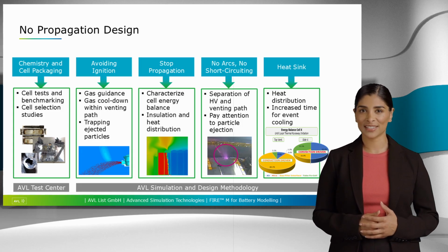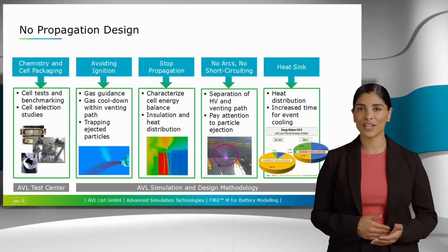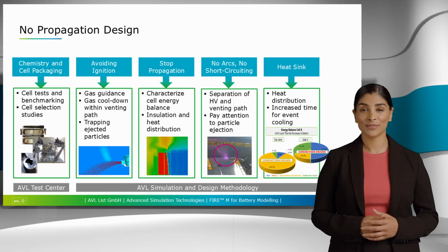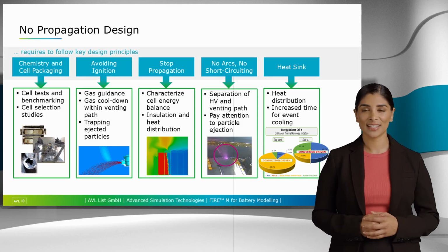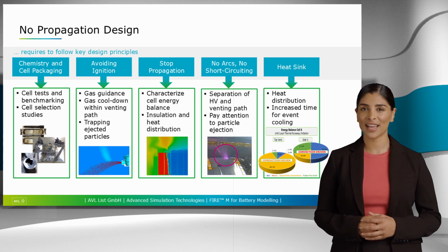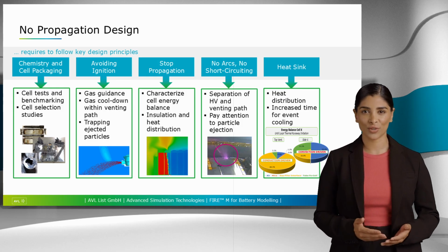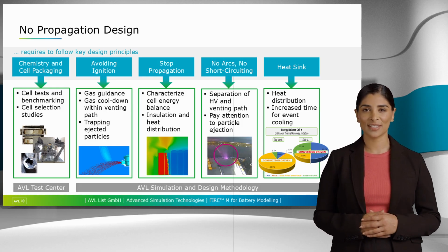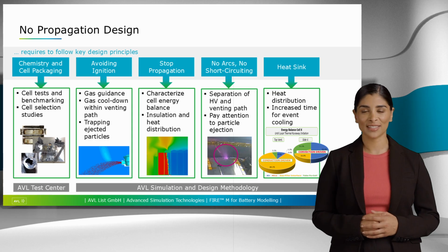Implementing dedicated heat sinks is also a means to help stop a thermal runaway. As you can see, our solution for a no-propagation design of batteries is strongly supported by simulation. But AVL also offers conducting physical tests required to characterize battery cells. These tests can be conducted in our AVL Battery Test Center.